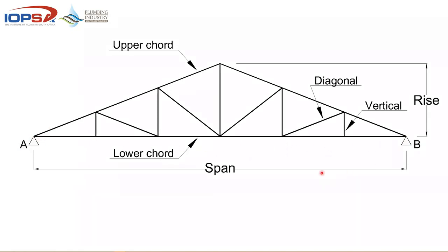The strength of the roof truss is born from a term called triangulation. In other words, the moment you have these triangles, and you can see there are quite a number of triangles in this little detail here, that's where the strength of this whole truss comes from. So for you to be point loading anything in specific, years ago we used to put wedges between the tie beam and the top of the internal wall to help bear weight. Nowadays, with these lighter trusses, if you point load anything, you actually cause the truss to buckle, because you're taking that triangulation away and you're splitting a triangle in the wrong position.